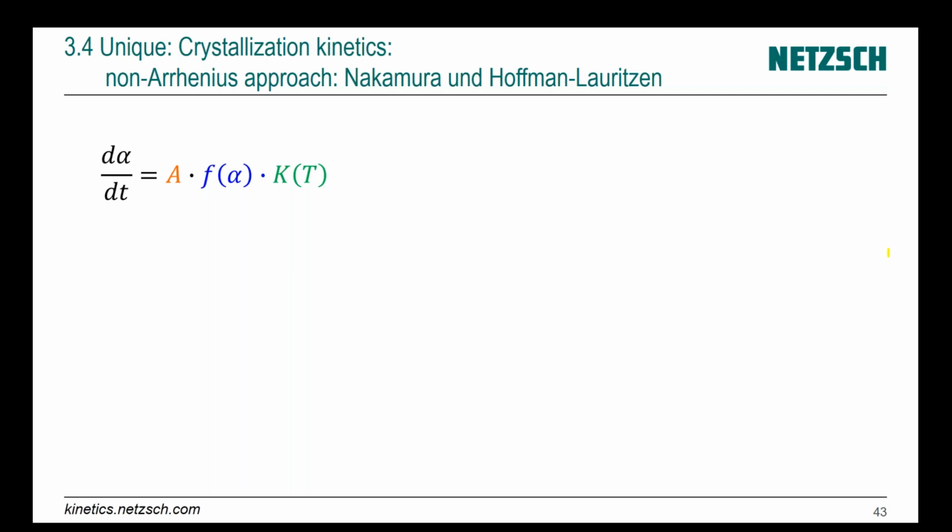Crystallization is very important for users who work with thermoplasts and requires fast cooling. For example, during production of plastic PET bottles. Do you like transparent plastic bottles or not transparent? So do you want to see what's inside or not? If you want to see it transparent, then we can find or simulate conditions where crystallization doesn't happen and material